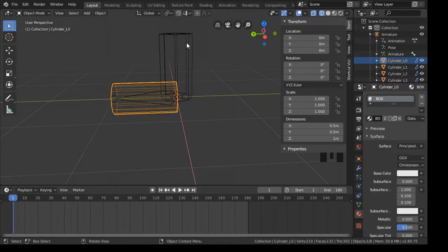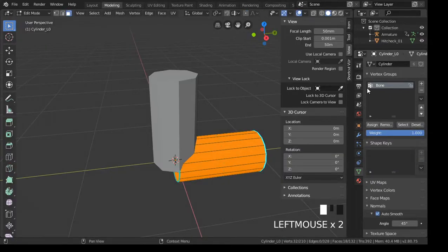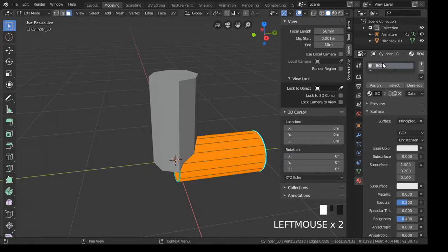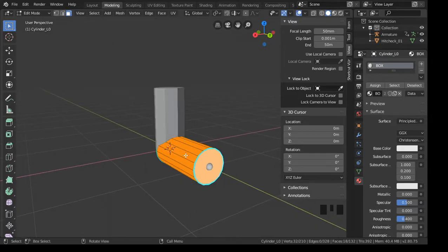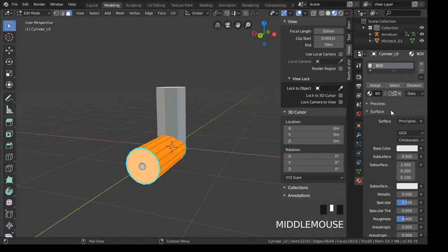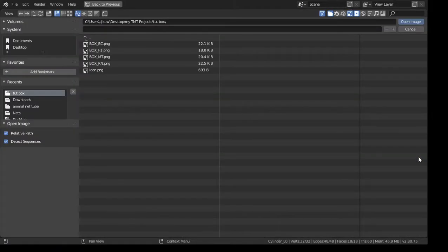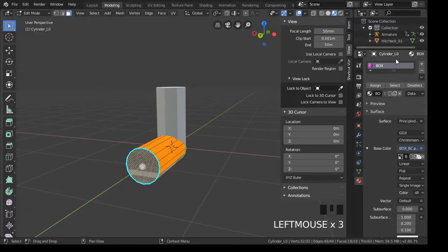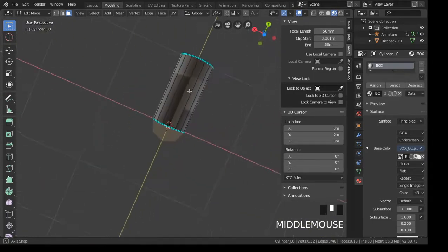So for this, the standard UV layout is a full box, so I'm calling it box, even though the object isn't a box. I'm just going to use that same texture for this model, so I'm going to call mine my material box. Now if you wanted to view the texture, right now you can't see it applied to the object, but if you click this one for shading, and then over here in your material editor for base color, click this little dot, and switch this to image texture, and then using the envelope here, you can load in a texture to look at on your model. And if you push A to get rid of the orange, you can see your texture applied to the object.